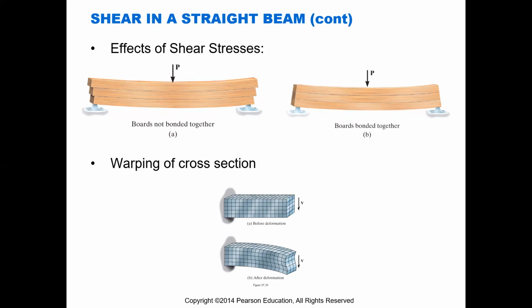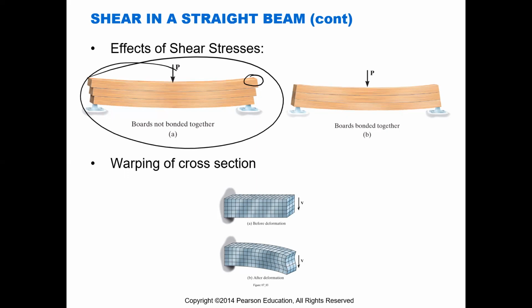But the bonds between the materials are what causes it to not have varying displacements of the ends. So the shear stress causes it to do that, right? The shear stress causes it to want to do that. Yeah, the shear stress is brought about by the fact that it's not allowed to displace. So like in between the plies in this scenario, there's no shear stress because they're just moving freely the way they want to. But then within each ply, so within this top member, there is going to be shear stress because that top member has to be moving together, right? This end right here is not having differential displacements.